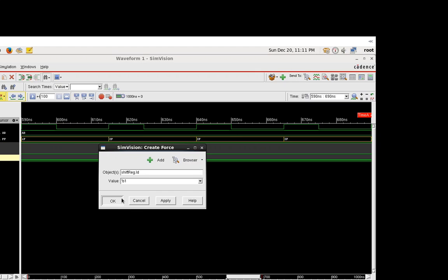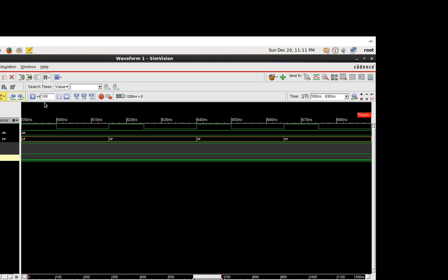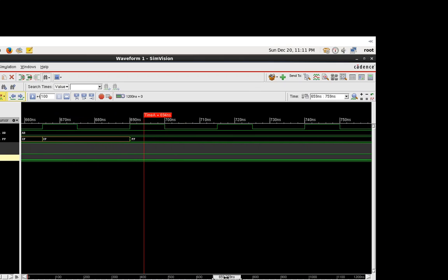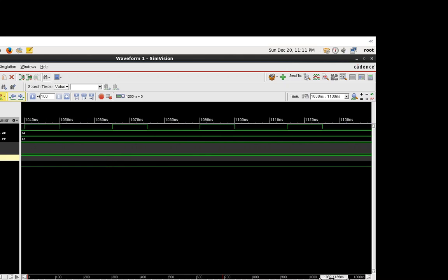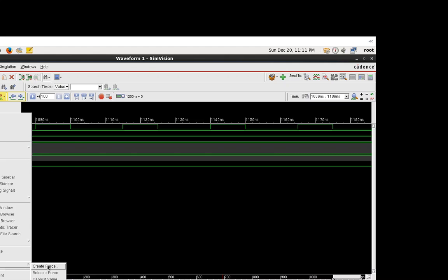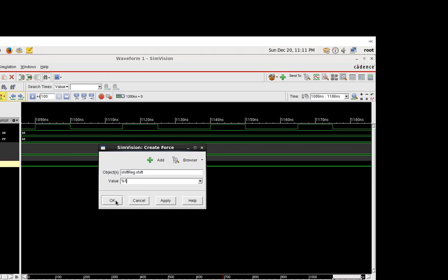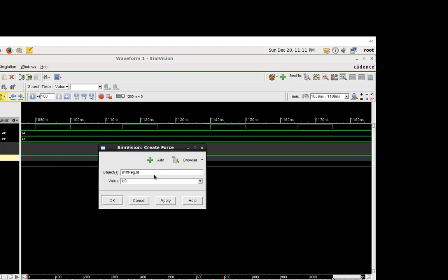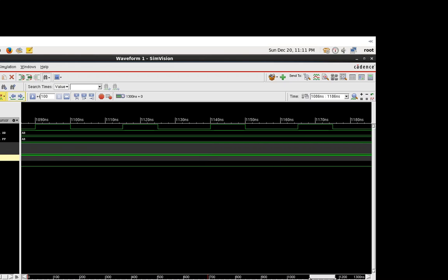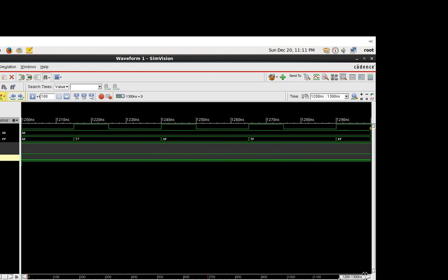So now what will it do? It will not shift the value, it will take here AB. It has made shift 0, load 1. So again it loads AB. Now with Sn equal to 1, let us again go back to shift operation. Simulation, create force. And load, make it 0. It's not correct to have both. We cannot be shifting and loading simultaneously, as that will result in erroneous operation. So now we see the shifting from AB to 57, AF, 5F, BF, etc.